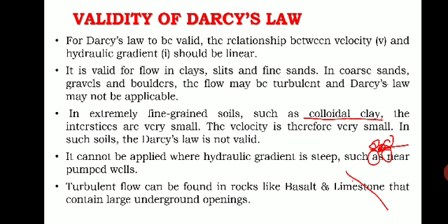Basalts have cavities because it is a volcanic igneous rock, and limestone, whose composition is calcium carbonate, CaCO3, has underground caves which are formed because of the dissolution of the rock by reaction with water. So such rocks may contain large underground openings, and here the flow will not be turbulent. So Darcy's law is valid.